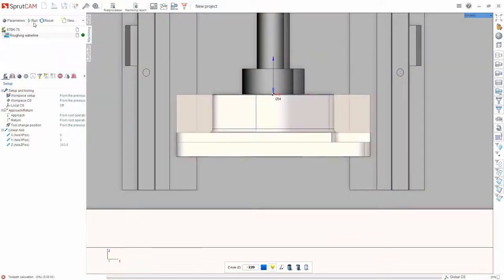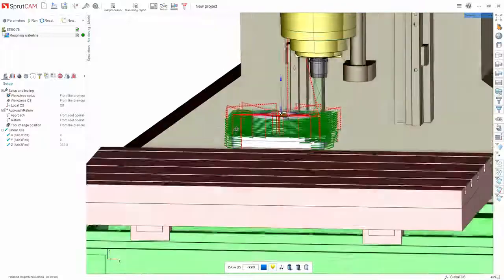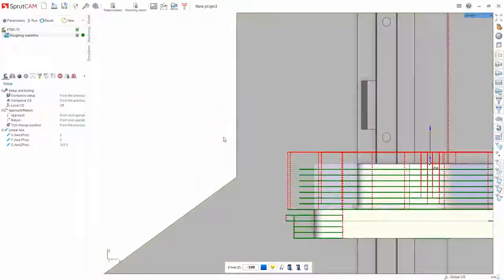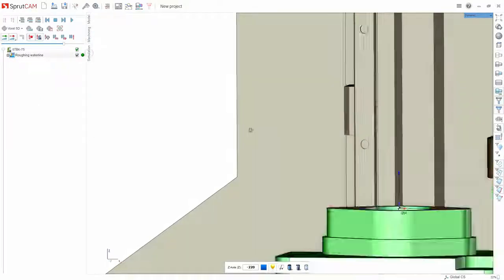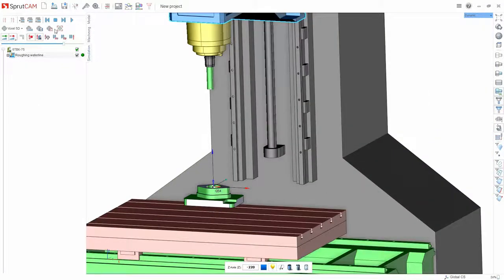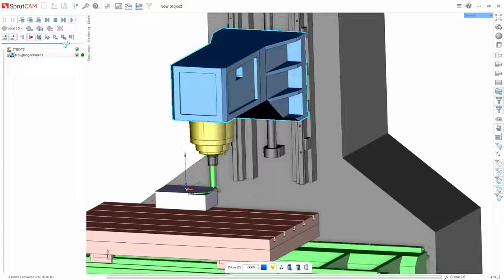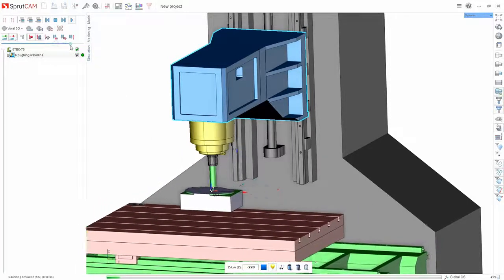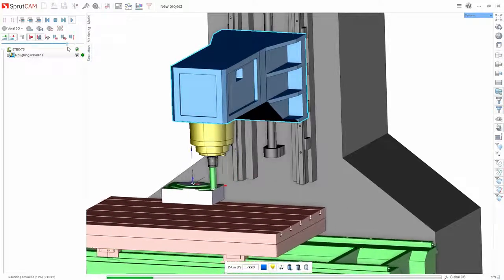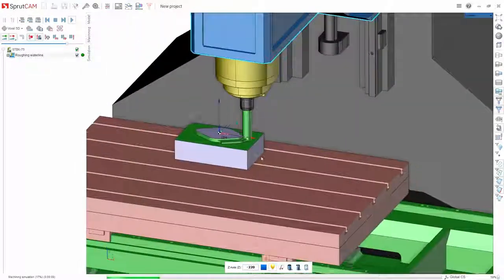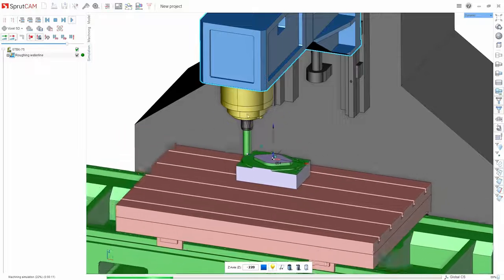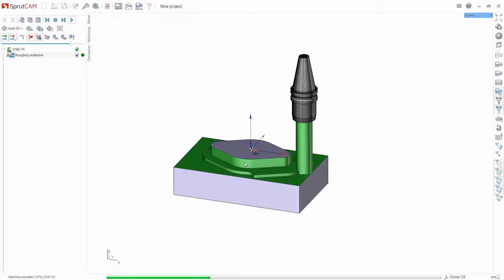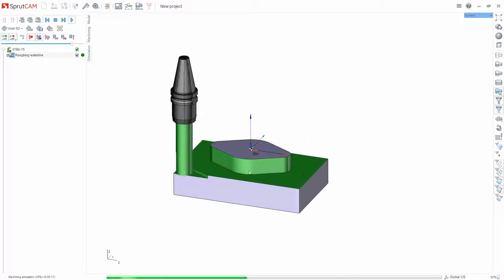Click OK. Run. The toolpath is calculated. Now the distance between the layers is 5 mm. Switch to simulation. Reset and run smooth modeling. You can always click Simulate All and see the result of machining. Look now, when the scheme works, the part is moving relative to the tool. The tool is in place.